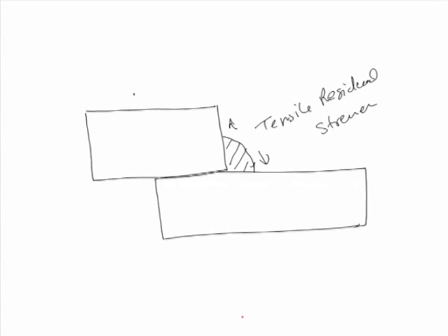So, to avoid this kind of cracking tendency in case of the fillet weld, minimum fillet weld sizes have been identified by the American Welding Society, and according to that, some minimum size of the fillet weld must be deposited for a plate of the given thickness. These minimum sizes of the fillet weld, as given by the American Welding Society, will be shown in the next slide.